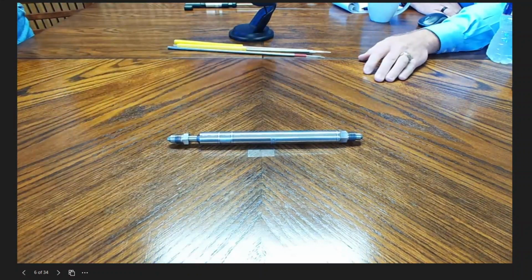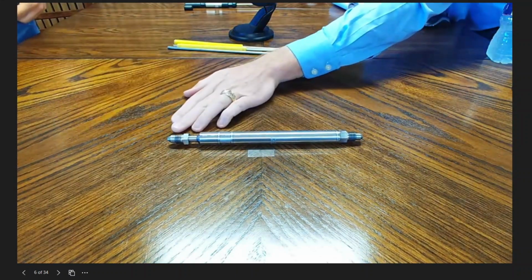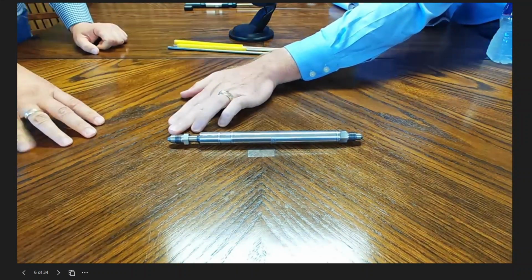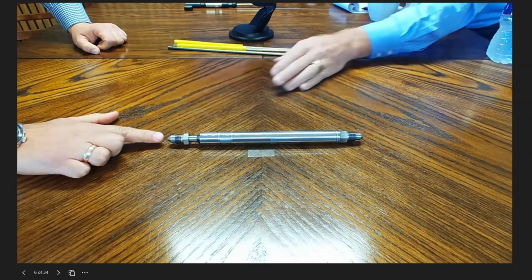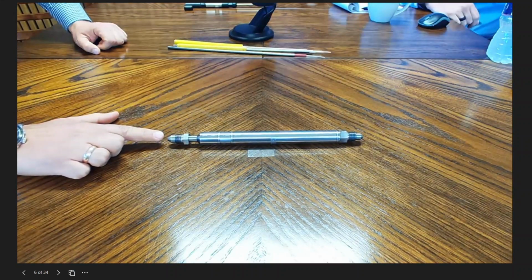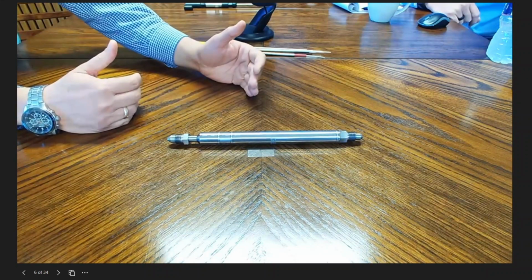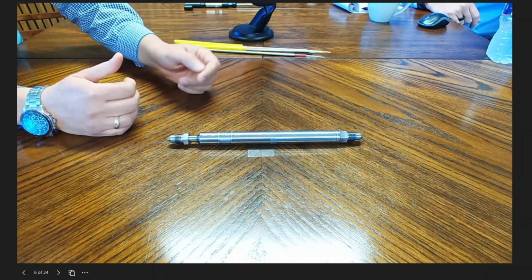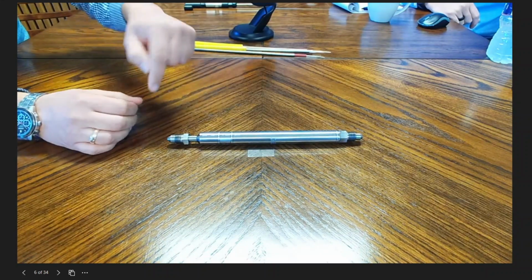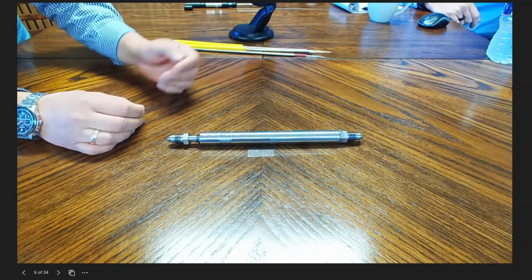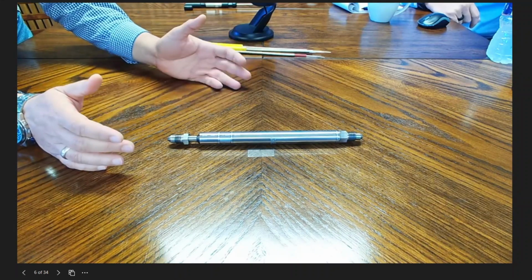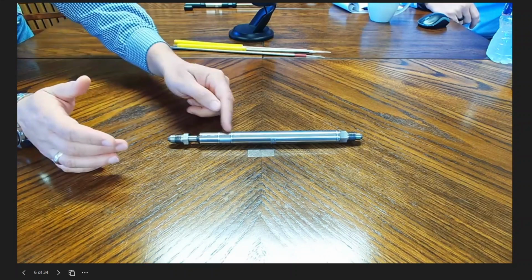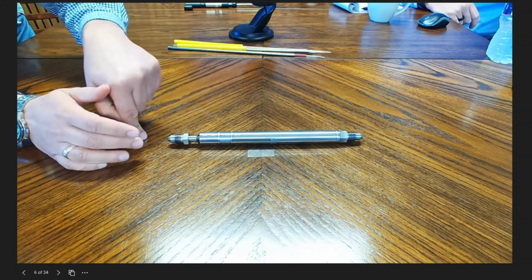So when you show this to us, Juan, the pressure from downhole, either tubing pressure or annular pressure, is going to be registered from this end there. Correct. Now, our gauge carriers all have communication internally to the tubing. So if we run the gauge carrier only, without the annular adapter, the gauge will sense the pressure inside the tubing.